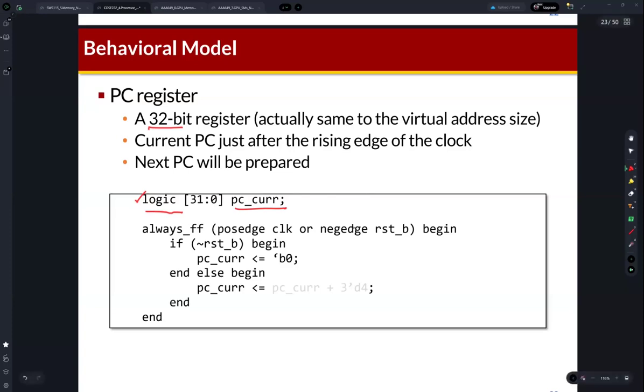You can find that we need to use always_ff. It means that it will generate flip-flops. FF represents flip-flops, and in order to generate flip-flops in SystemVerilog, we need to use always_ff. It is synchronized with the positive edge of the clock signal, and it can be controlled by a reset signal. A reset signal is required for stable operation of a digital system.